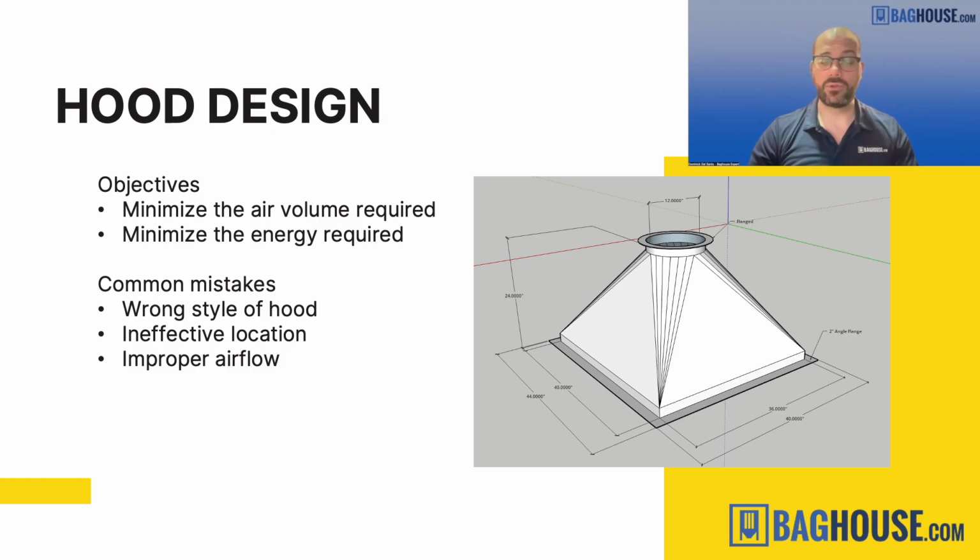All we really need to do is look at the machine and see what size the port is, or how many ports there are for dust collection on the machine. Now, it may say in the manual how much airflow you need to provide for dust collection, but even if it doesn't, if you look on the machine and find, for example, that there is a 4-inch round dust collection port sticking off the back of your chop saw, that's your key to figuring out how much airflow you need.